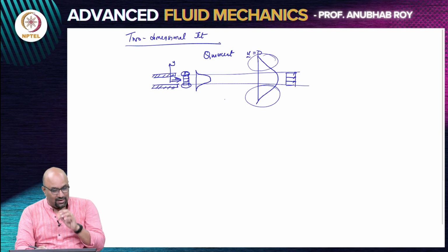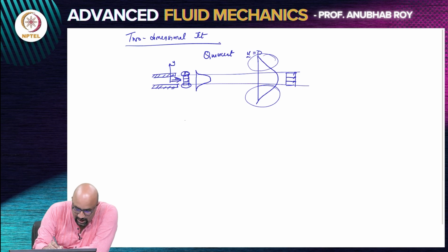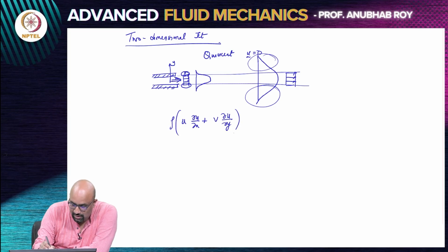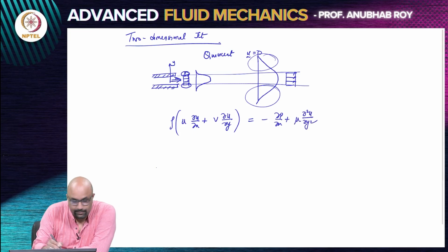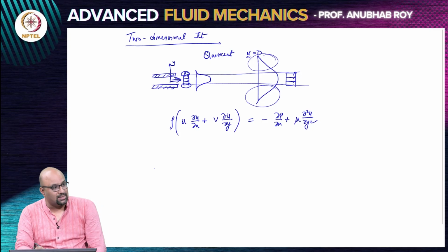So, we will try to see if we can make some headway into this particular problem using boundary layer theory. Now, the governing equations. Again, we are doing all of this because we are following the spirit of how Prandtl mentioned we should be studying these problems, that is, having the inertial acceleration being balanced by viscous diffusion. So, we are continuing with Prandtl's equation.